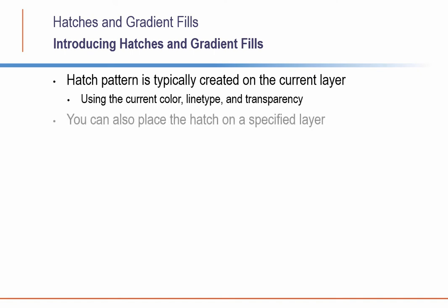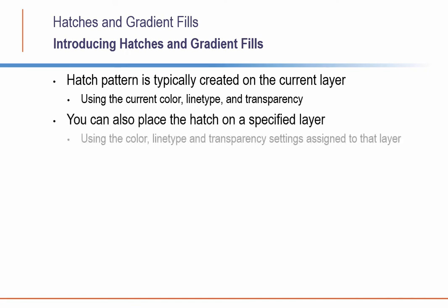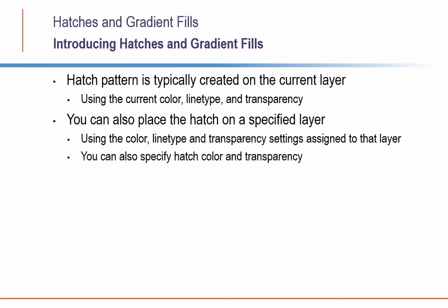You can also place the hatch on a specified layer using the color, line type, and transparency settings assigned to that layer. But you can also specify the hatch color and transparency explicitly. You can also assign a hatch background color.